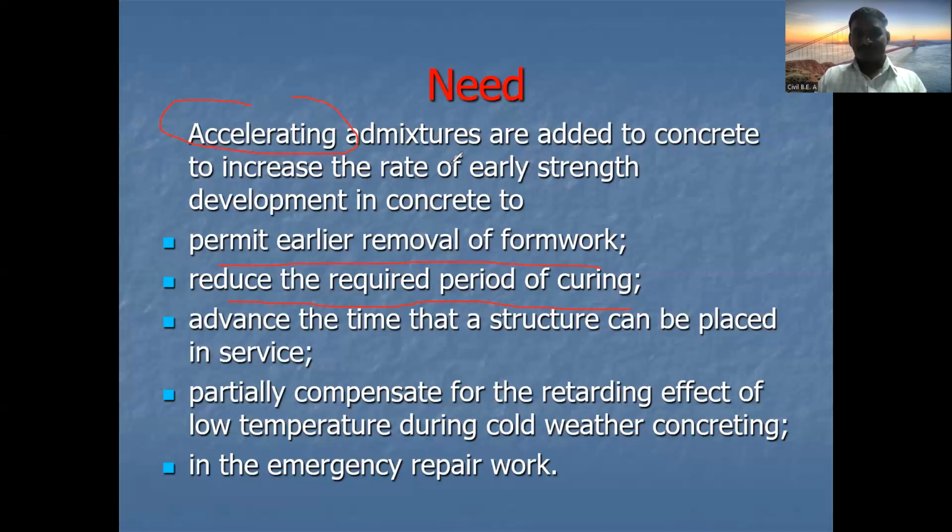But that 28 days curing period is one month. If we add the accelerating admixture, we can reduce the required period of curing also, and advance the time at which the structure can be placed in service.